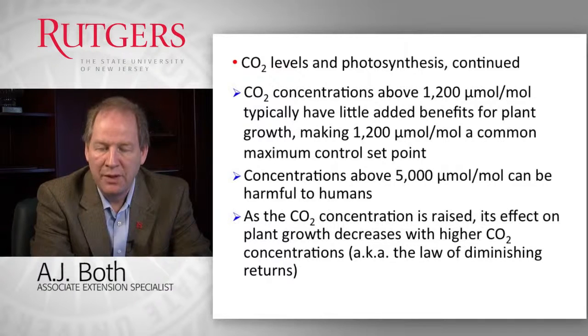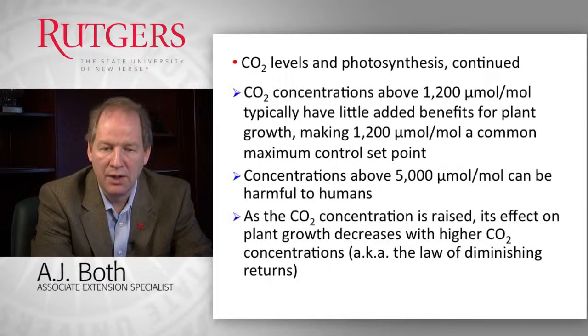We also have to be concerned about the impact of CO2 on people working in greenhouse environments. Obviously the CO2 concentration that we are used to is not a concern and is relatively low, but as we are adding CO2 in greenhouses, which is an enclosed structure, we could see high CO2 concentrations. When you reach a level of 5,000 or more, we start to get a little concerned. So you need to have equipment in your greenhouse that can measure the CO2 concentration and raise an alarm when CO2 concentrations get really high, because they can have a negative impact and at some point actually cause significant problems for people working in those environments.